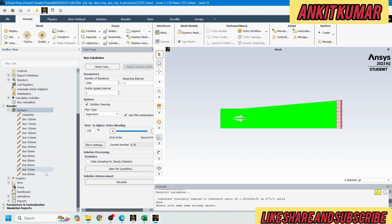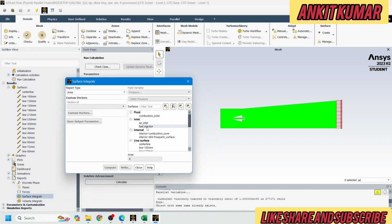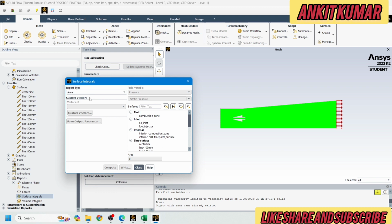Now I will calculate the different values at different points. In order to get the average value at different sections in the transverse direction, go to report. Here is a symbol called report. Click on this plus, then double click on surface integral. The first required value is density. From the report type, change to area weighted average, and from field variable choose density, and at line 50 mm choose line 50 mm. Here is the line 50 mm, choose this one and click on compute.